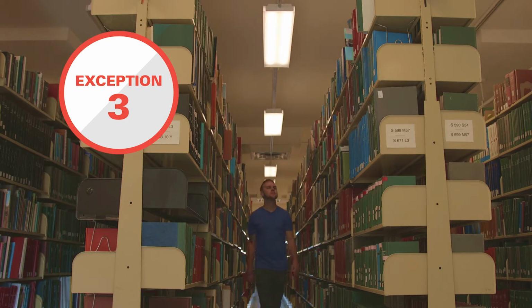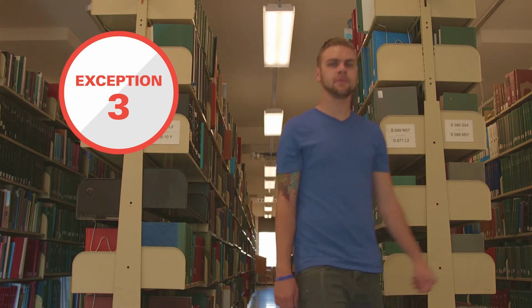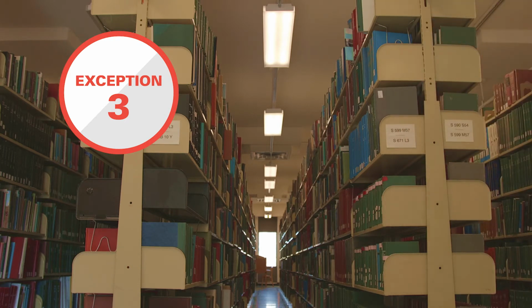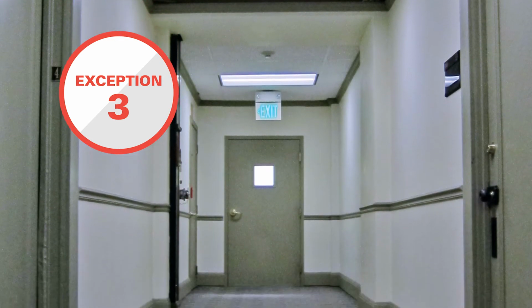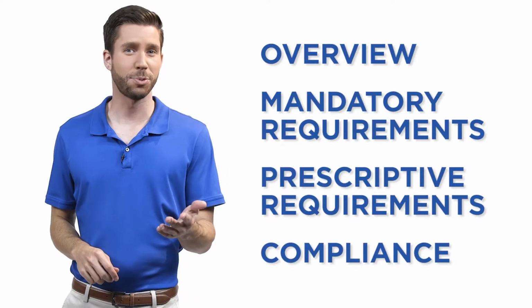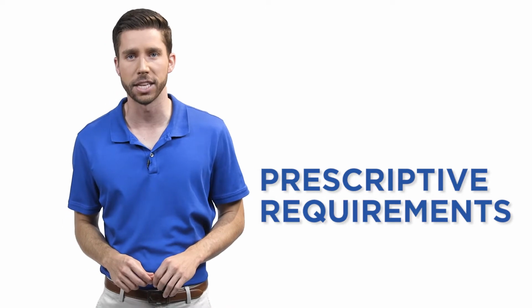These areas include aisleways and open areas in warehouses, library book stack aisles 10 feet or longer that are accessible from only one end, and library book stack aisles 20 feet or longer that are accessible from both ends, corridors and stairwells, parking garages, parking areas, and loading and unloading areas. Next, we'll review some prescriptive requirements directly related to multi-level lighting controls.